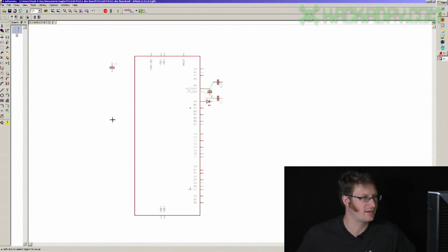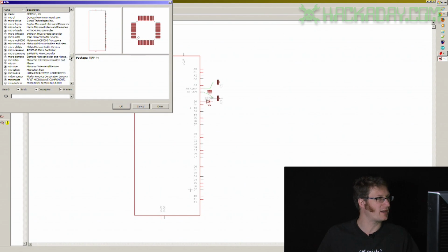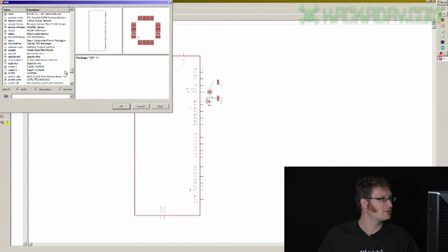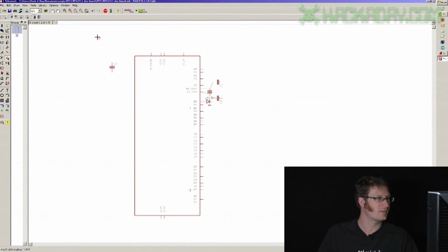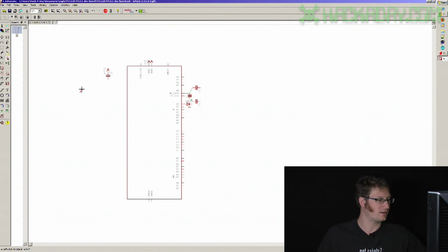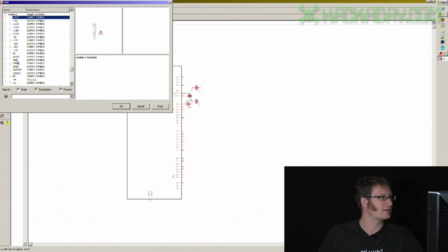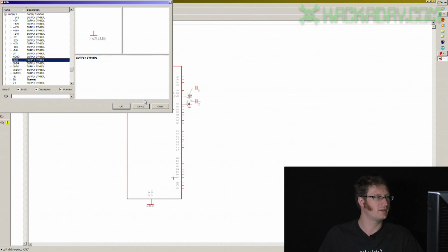One final thing before I just take you away from this section of it is that you need power. I am going to add, if I go into the supply section, supply 1, we'll just say plus 3.3 volts. And I'm going to put a capacitor there because this is our decoupling capacitor. There. I'll hit escape, and I'm going to select ground, and I'm going to connect ground there and there, and we actually need another one over here, one here.